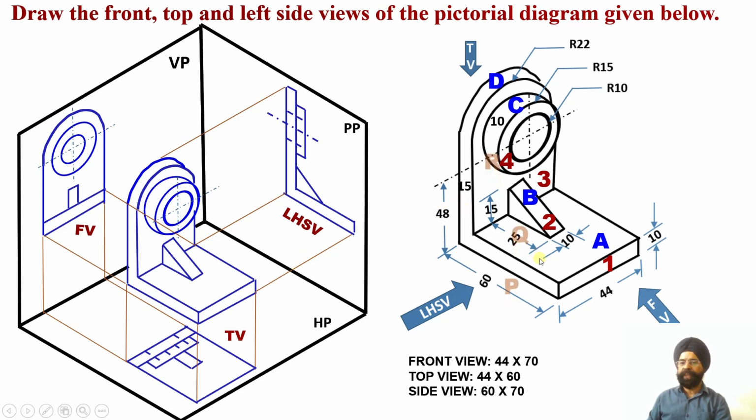Now let's look at the surface from the side. Here my surface P is there. Up to this center point, that is, from where this arc is starting, this portion of the surface P is true shape, but beyond this, the portion corresponding to the circular portion is my apparent shape. So I cannot say that the entire surface P is true shape. We will say that surface P is represented as apparent shape onto the profile plane. This is my profile plane.